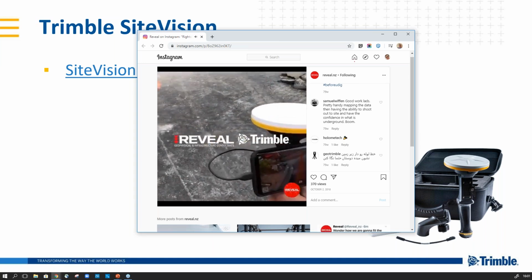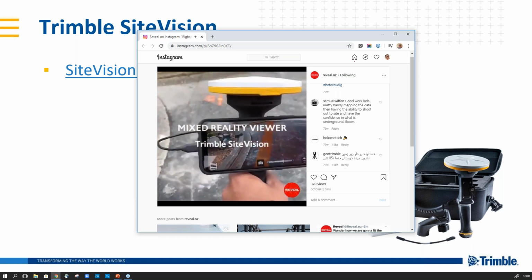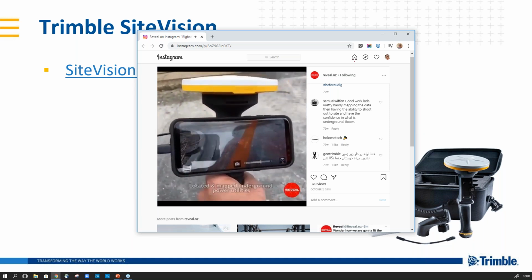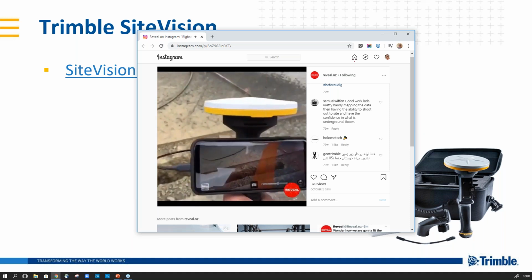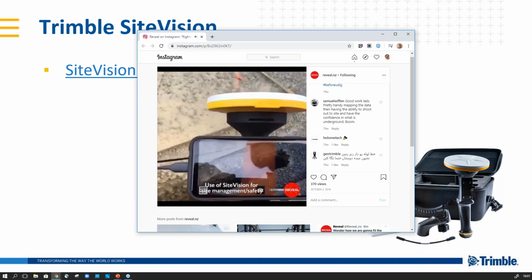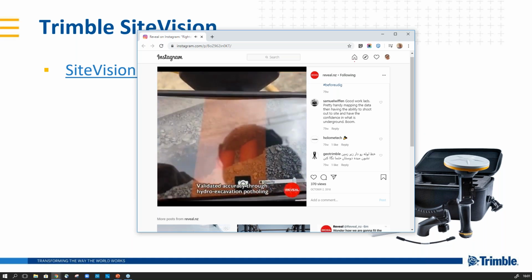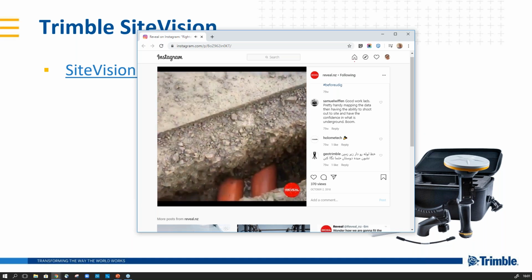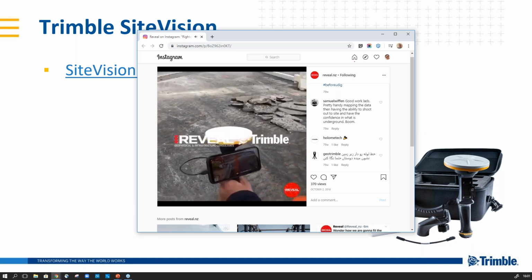So this is a real situation where they've taken an asset layer and actually done a pothole to check where this particular layer is. And as you can see, when they get up to that dug site, you can see a pipe underground there, and that line actually lays directly over the service there, which has given it validation that it is in fact correct. Thanks, Jonathan.